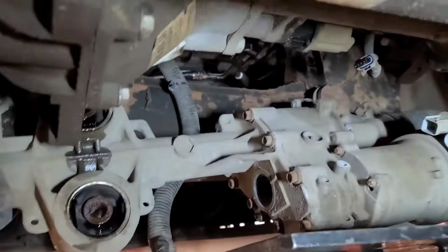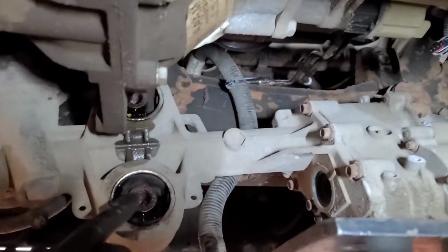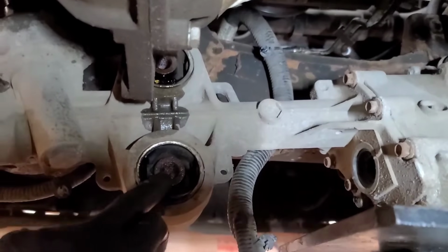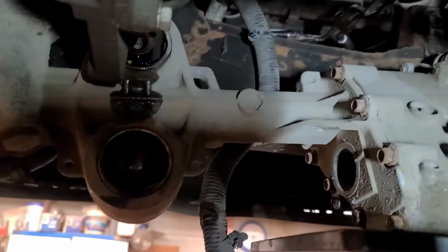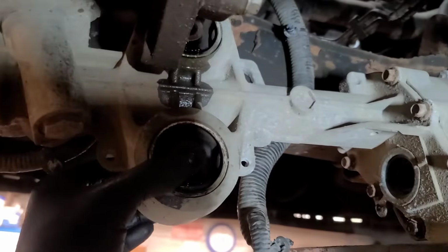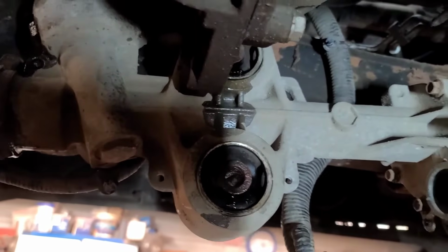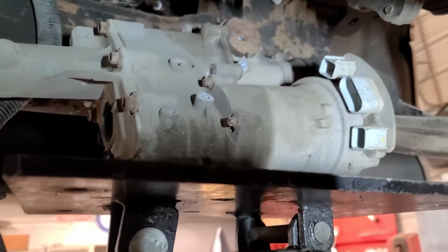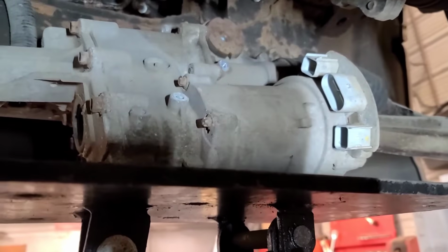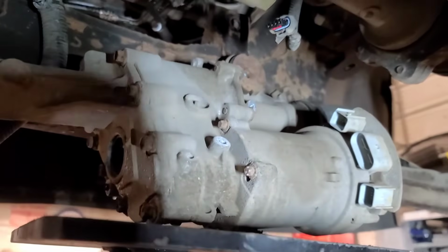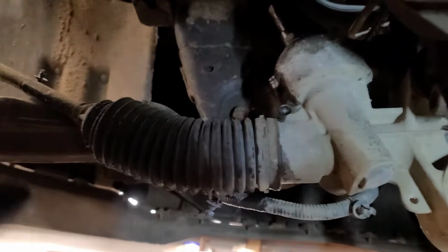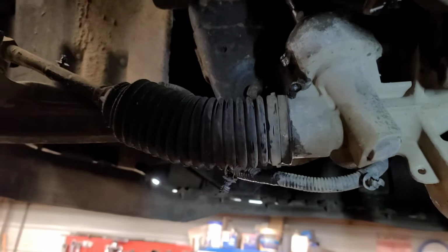So there's actually 4 bolts that hold that in. 2 of them have 15/16 heads on this side, and they're in a rubber bushing, so they don't come out with an impact gun because the bushing just absorbs the torque. And I just put this jack stand underneath here because I wasn't sure how heavy this was going to be or how awkward it was going to be to remove. So I'm going to lower it down enough to get this and move it to the right enough to get this side out, and then hopefully it'll come out of here.